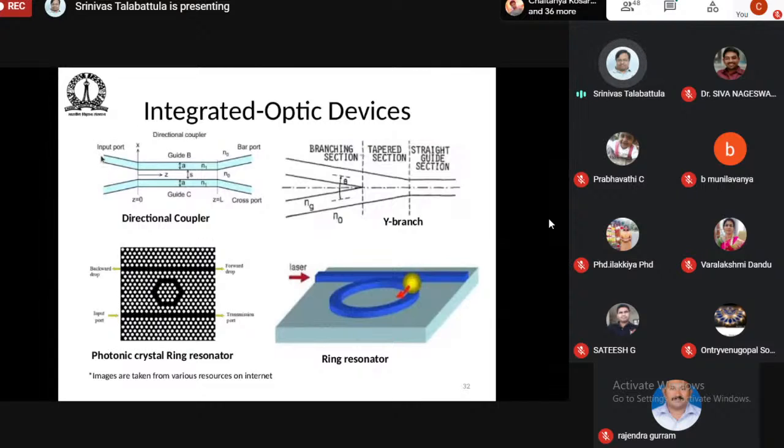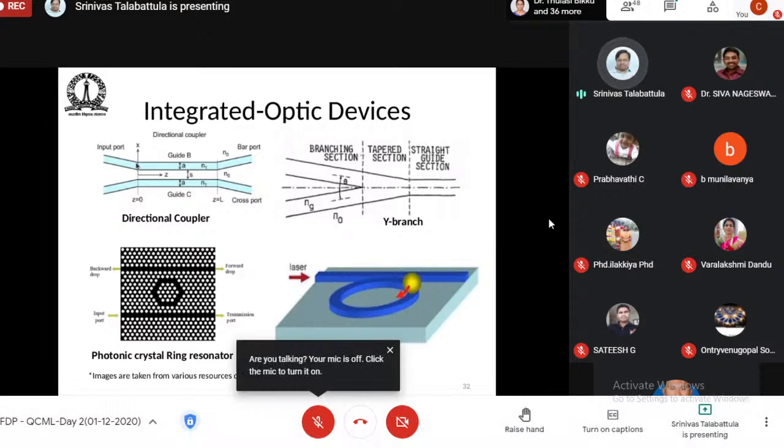So single photons, if they are launched into the ports of this directional coupler, then what happens? Traditionally, in the conventional sense, you would say that the power is exchanged between these. So 50% of the power can exchange from this to this. But in the quantum world, you cannot divide the photon. So you can say that the state of a photon at this point is a superposition of the states of the photon which could exist in this waveguide or in this waveguide. This is a truly good example of a superposition of states. And of course, because there are 2 input ports and 2 output ports, this device will manipulate.